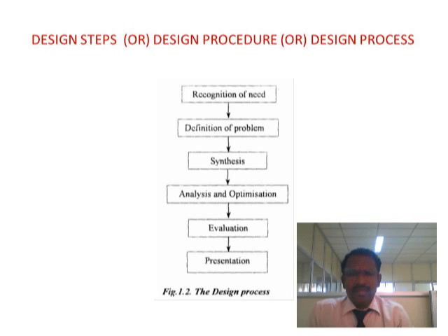Analysis means you have to find out the forces acting on the component by using strength of materials concepts, engineering mechanics concepts, etc. After that, we have to select a suitable material for the particular application. Then after analyzing these things, you have to fix the dimensions for the component.